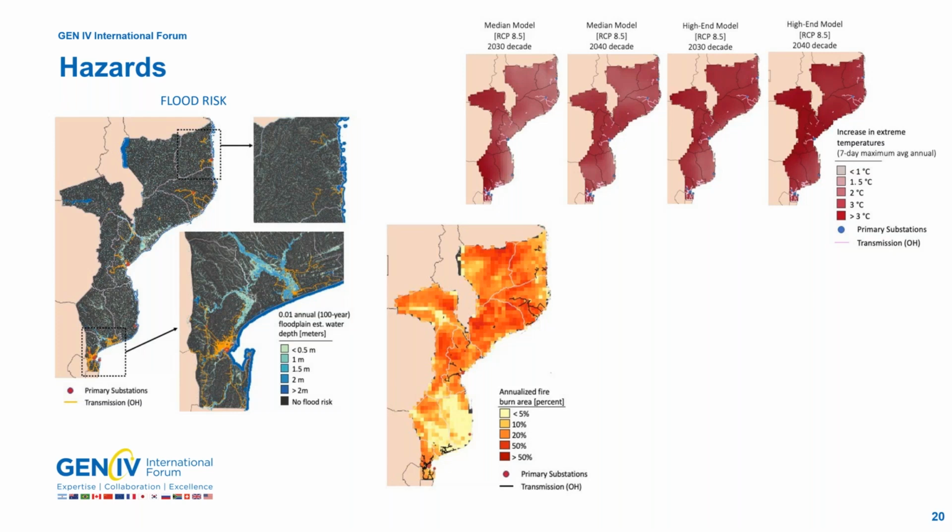Increases in temperature also affect generators. Typically, generator efficiency goes down as the temperatures go up. And there is a small penalty from the Carnot efficiency, but with fossil fuel generators, the combustion process actually becomes less efficient because the density of air goes down. So it'd be less of an issue for nuclear power generators, but the efficiency of those generators decreases as the temperature goes up. And if you're expecting hotter temperatures in the future, you have to design the systems to encompass that.